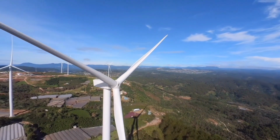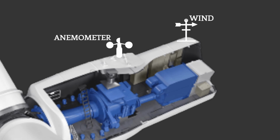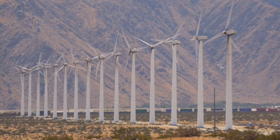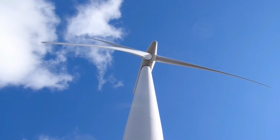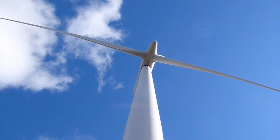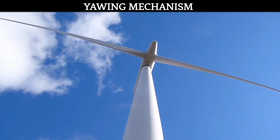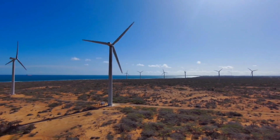To help with this, there is an anemometer on top of the nacelle, which measures wind speed, and also a wind vane which determines wind direction. The real-time data is used by the turbine's control system to adjust blade pitch and yaw angle, ensuring efficient operation under varying wind conditions. This is known as the yawing mechanism. The orientation of the blade also determines the efficiency of the wind turbine.